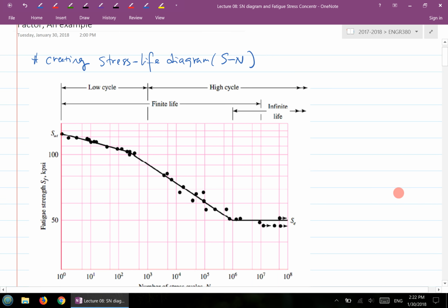There's one question that you should think about. We're talking about fatigue loading. So one question is, do we design for an infinite number of cycles, or for a finite number of cycles, based on certain loading conditions? The loading condition could be given. Say the part is subject to completely reversed loading of 100 ksi amplitude, for example. And then the next question is, how many cycles would it fail at? Would it fail at a number of cycles greater than 10 to the power 6, which is infinite?